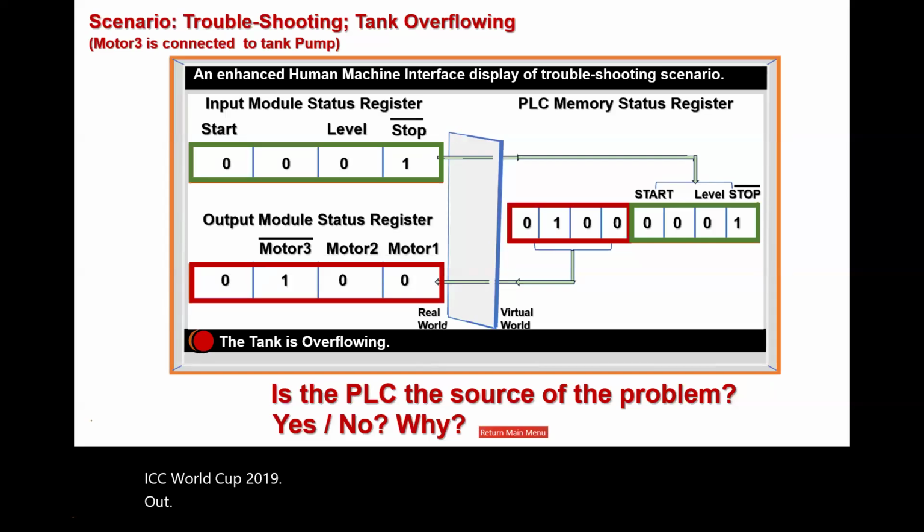Well, going backwards, the previous slides, motor 3 was the player. And what is the information about motor 3? Is it an active high or an active low device? It's active low, right? How do I know that? Well, I looked at the I/O port maybe earlier, but it's also when we programmed this thing, we made sure the label had a line over it, right? So this whole image, motor 3 with a line over it, means motor 3 is an active low device. Maybe I don't know how to wire it that way, but that's the way it is.